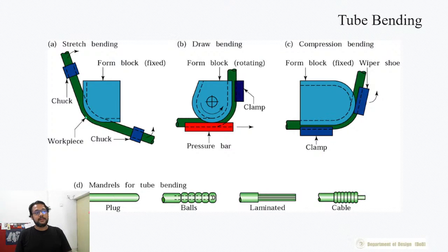To stop the tube from collapsing, you would put in mandrels. These are flexible pieces which provide structural stability to the pipe when it is being bent. Bending a pipe is a forming operation. It's not really a bending operation. That means you would have to stretch it and give it that shape instead of just collapsing it onto itself.